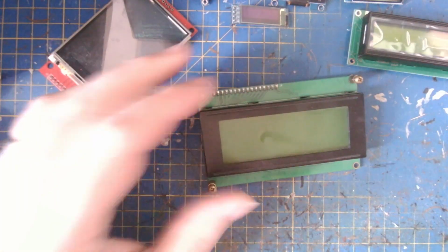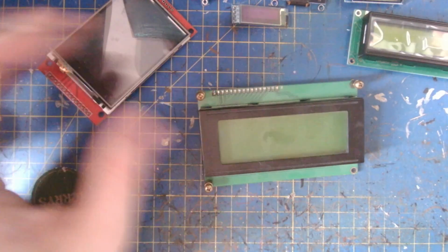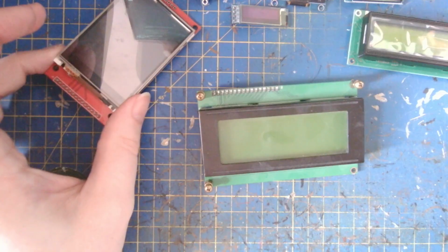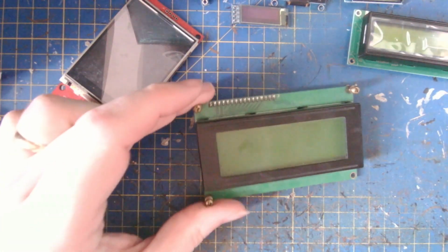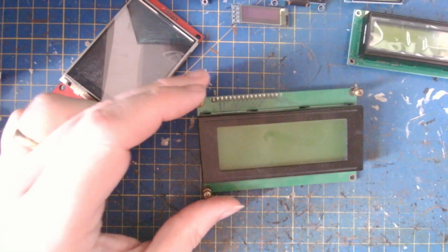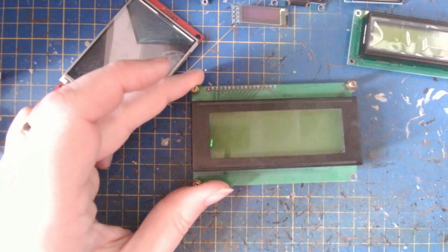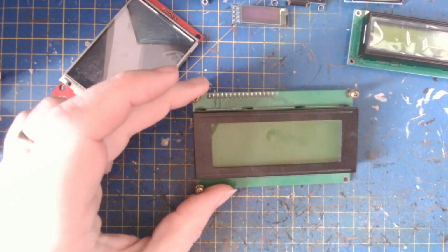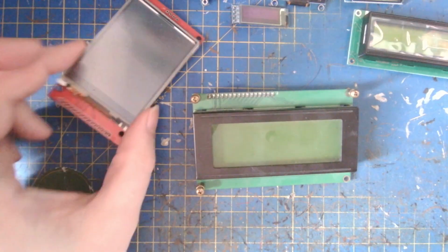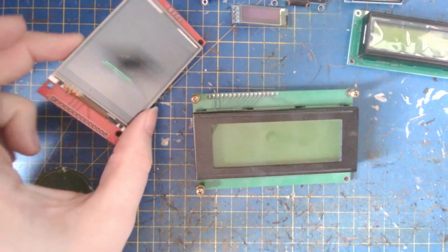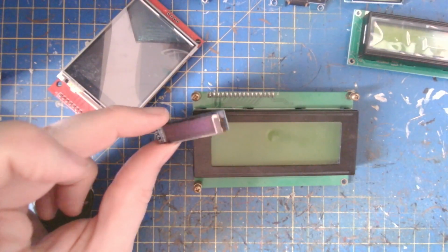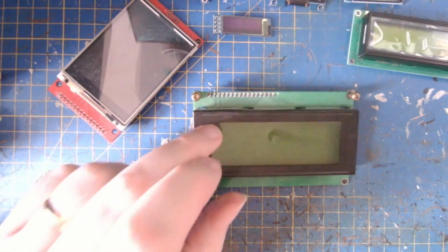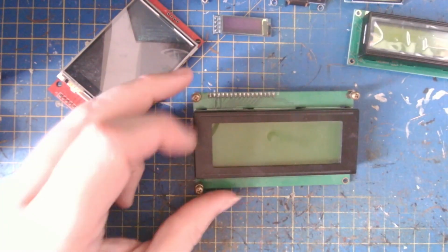So I2C screens, like I say, very easy to connect. SPI screens much faster. Another consideration is availability. Now, as you can see, I've got a few of these things. I'm going to use this. It's quite suitable to use with an Arduino Nano, but I could use this. I've got it. For what I'm going to use it for here, it'll be complete overkill. In fact, that would probably be perfectly adequate. But this is a bit bigger. It shows up on camera a bit easier.